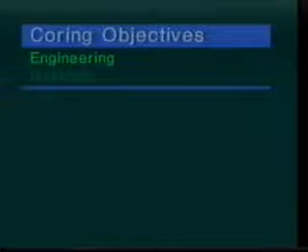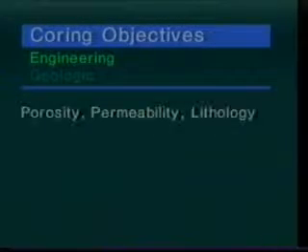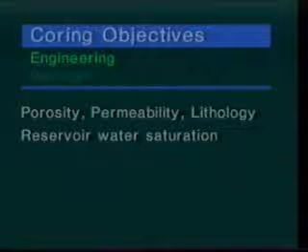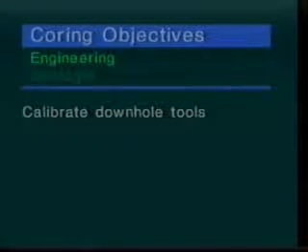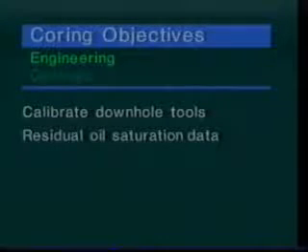The engineering objectives include the definition of aerial changes in porosity, permeability, and lithology needed for reserve estimates and mathematical models; to define reservoir water saturation; to assist in the definition of net pay thickness; to assist in calibrating downhole tools; to provide data on residual oil saturation, especially for enhanced oil recovery studies;